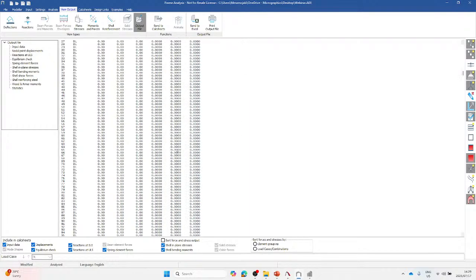I am just going to scroll down, and let's check under Y from node 123. You will see that's when the deflection will start showing, and you will see it is 2.26, 2.27, 2. So that is why I say, based on how I modeled the slab and the spring elements, it does look like the deflection is uniform throughout the slab.